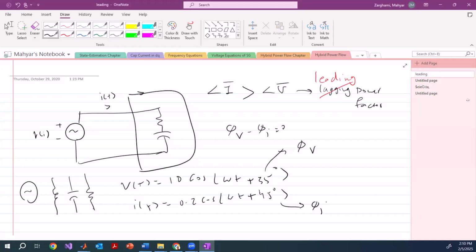So reactive power is the representation of the power that is going to be exchanged between these three elements: the inductances, the capacitances, and the source, the power that just circulates between these without doing any work. So overall, on average, there would be no power consumed or generated between sources, inductances, and your capacitors. So their action would not be causing any power loss.